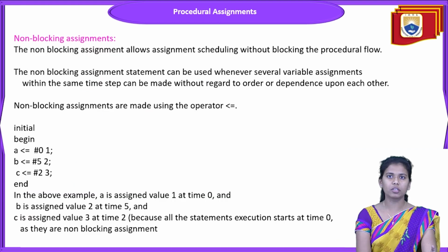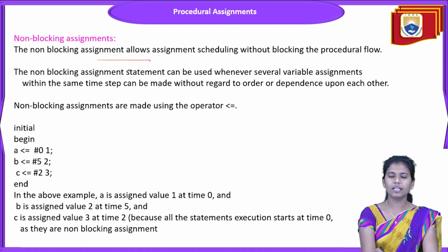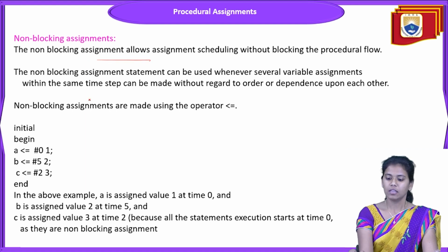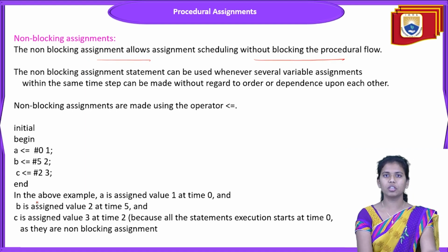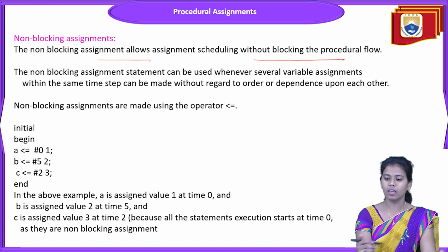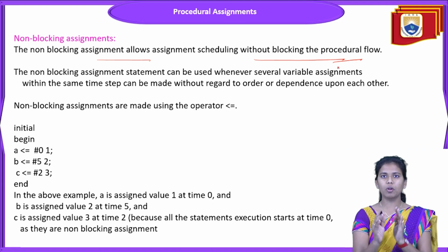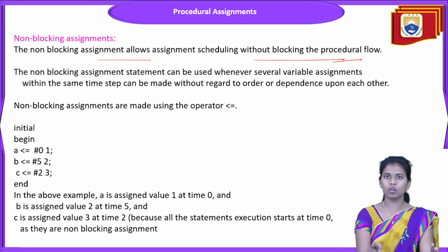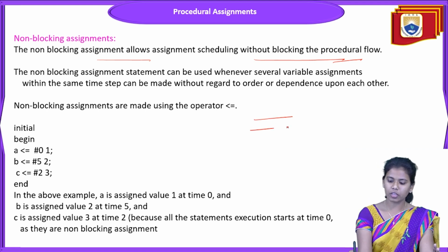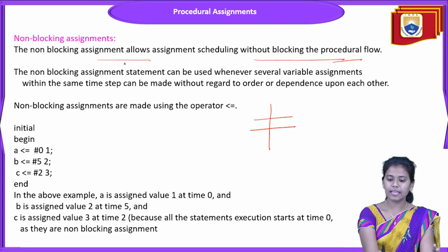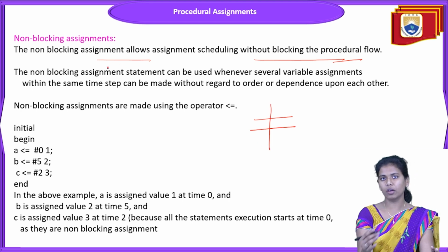And coming to the non-blocking assignments. So what is this non-blocking assignment? The non-blocking assignments allow the statements scheduling without blocking the procedural flow. So these will schedule the assignments without blocking the procedural flow, and the assignments just keep on executing.